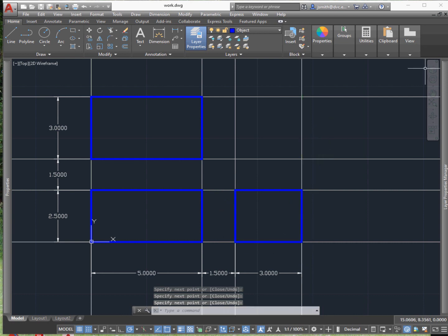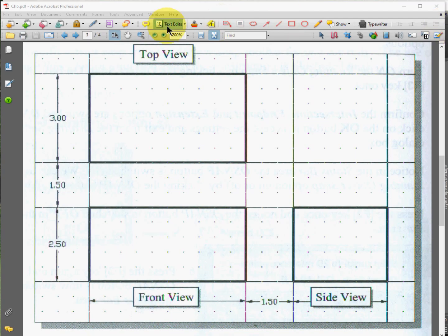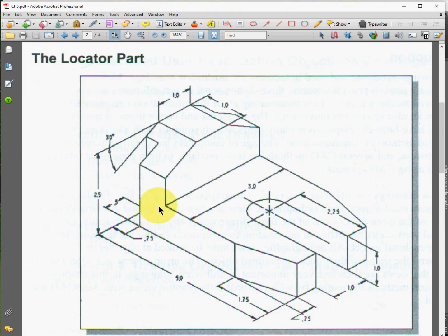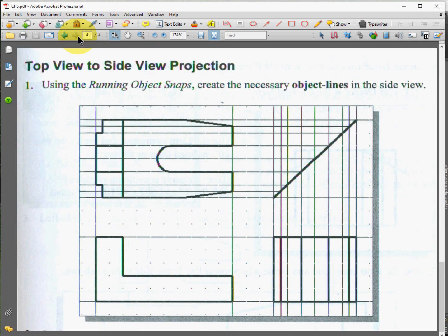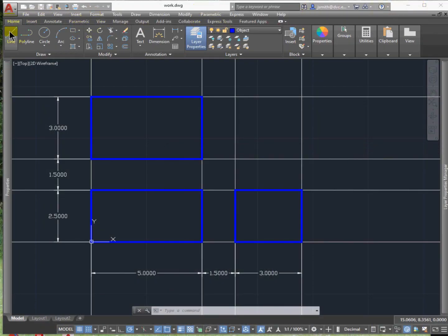And so when you do an orthographic drawing, everything must line up. So all the lines must line up. That's why we're using construction lines. You can try it without construction lines, but I guarantee you it won't be accurate. And then you're also going to see this 45-degree angle in that top right box that we're also going to use.